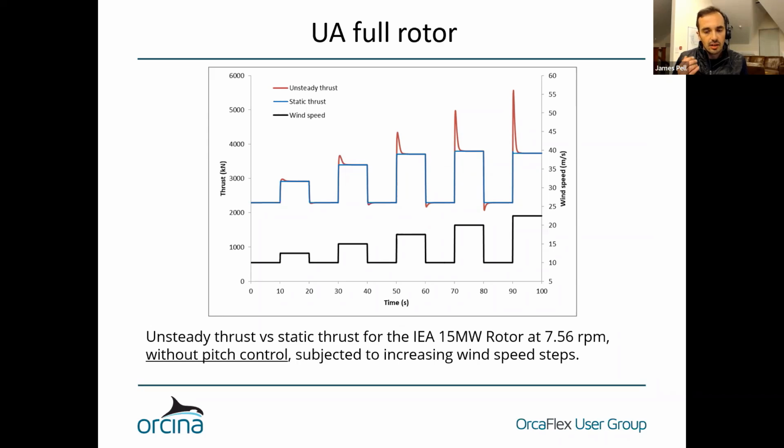Including these unsteady aerodynamic models, which affect the blade's damping, essentially aerodynamic damping, can significantly suppress that instability. As a result, it makes the models far more robust, so far less likely to fail due to extreme blade flutter. That seems to be a nice byproduct, as it were, of including these models in that reference wind turbine.